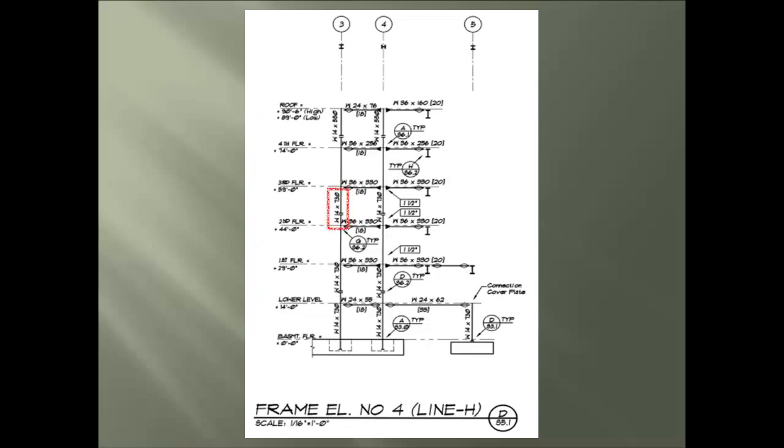We see the column size callouts, and then the beam callouts. Notice the special moment frame and drag strut connections. Here is a symbol for column splices. And lastly is the call out for the orientation of the columns required for the frame. As with the other two views, the elevation view offers a tremendous amount of information.